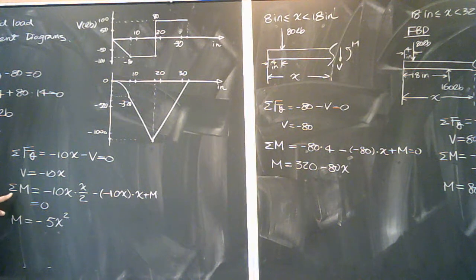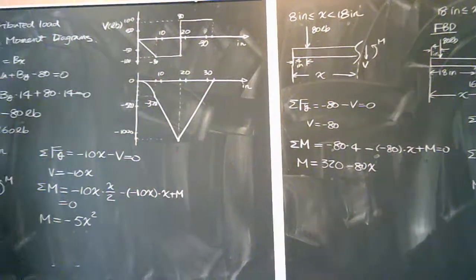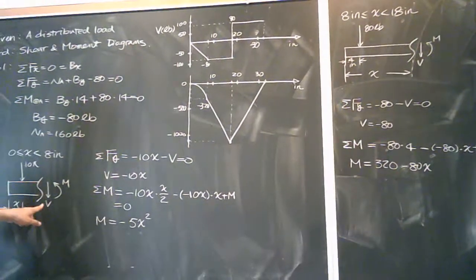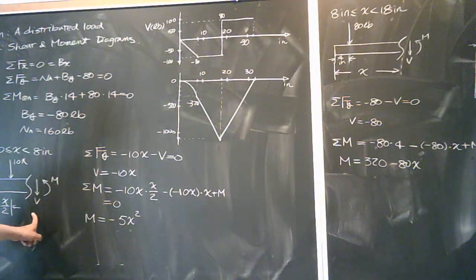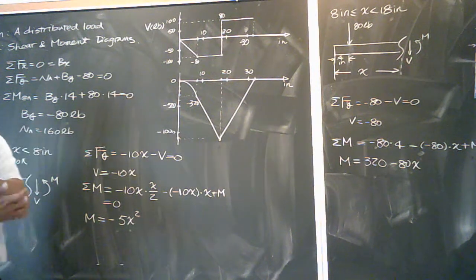Number 2, if you have a moment equation other than the moment in this free body diagram, you also need to consider the moment created by your shear force. The shear force is the equation you get from your force equations in each section.